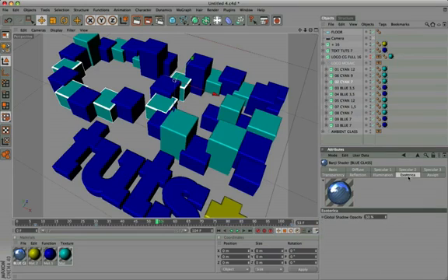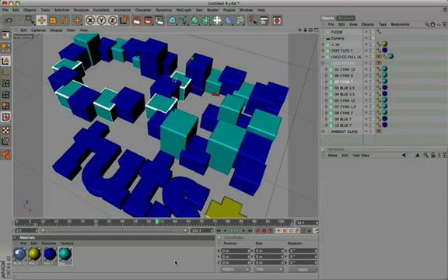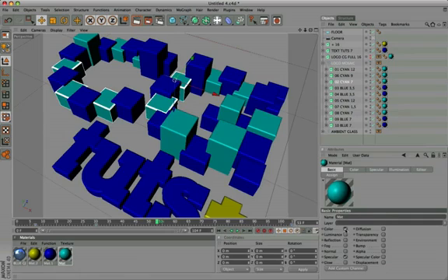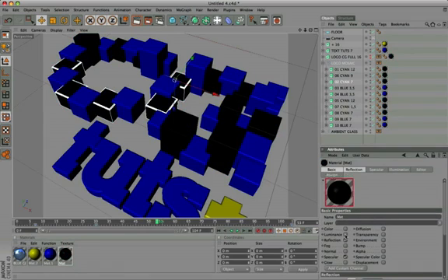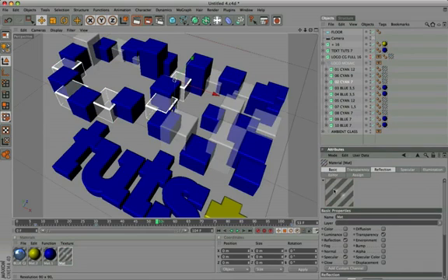The illumination panel is by default. In Specular 2, change the value of intensity from 20 to 60. In the Basic panel, turn off color, and activate reflection and transparency. Rename this material cyan glass.